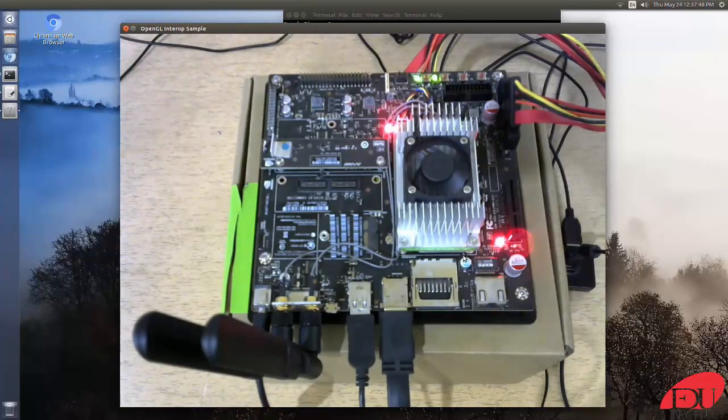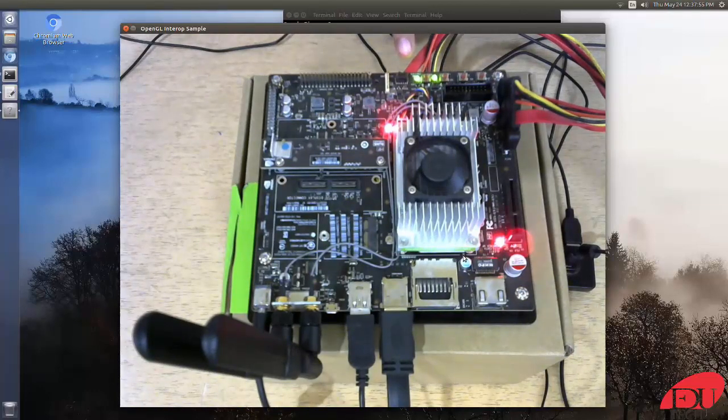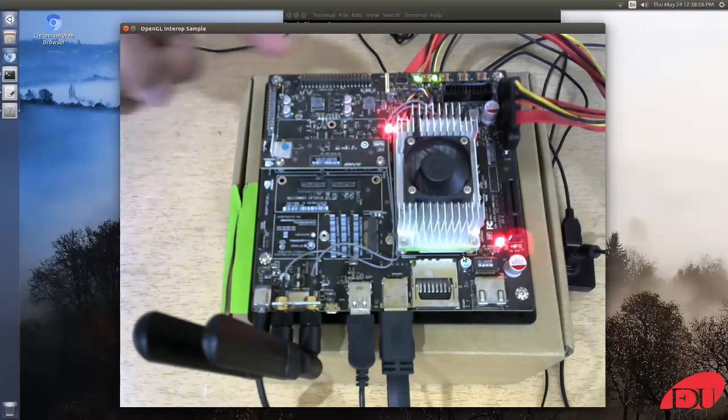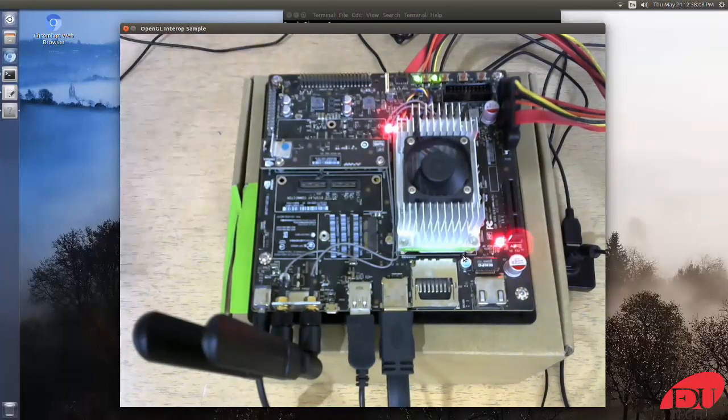Okay, we will talk about this much more in depth later on. You can see there are these 4 switches for controlling the board: shutting down, switching on, or putting the board in flashing mode. Okay, if you want to flash the board with different sorts of operating systems. Then you can see there are 2 GPIO pin connectors, which contain a lot of protocols within them, like I2C, SPI, CAN bus, UART.